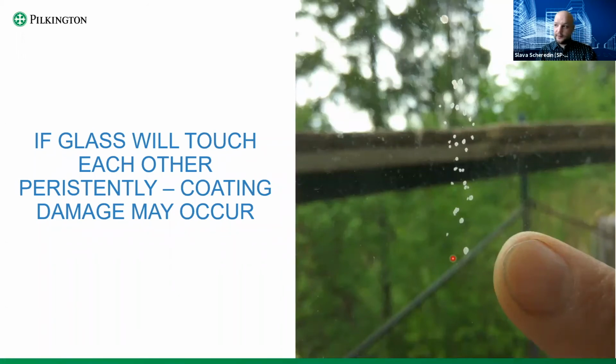Second one, it is good to think about your agreement with the private customer and underline there that, okay, after the IG unit installation or window installation for that matter, the conditions should be maintained in accordance with the requirements of the European regulatory standards or Russian standards for that matter, because our GOST clearly states under which conditions an IG unit should be used, meaning no negative temperature, and the inside of the building should be heated.